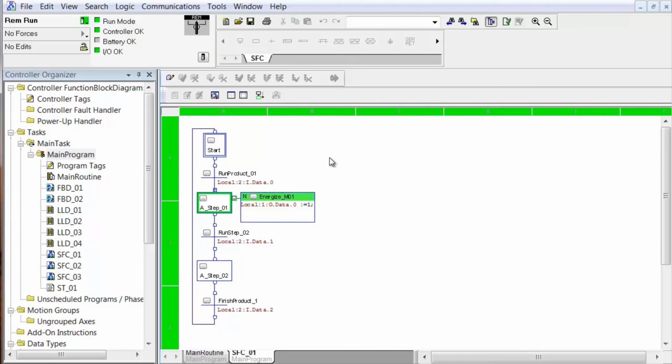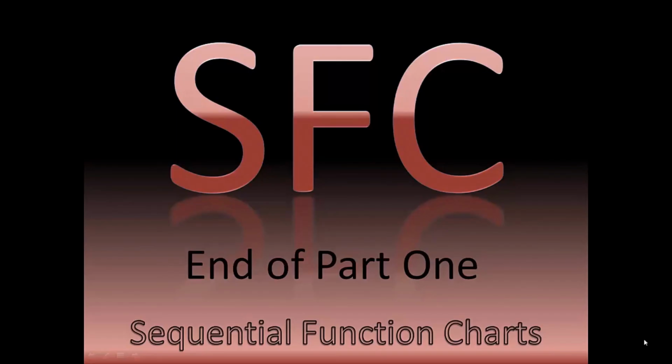This is an extremely important characteristic of sequential function chart, transition, and step. Also make note that the action stayed active until you transition into the next step. That's because it's a non-stored action. So now we'll change the qualifiers to something else and see how the behavior changes.